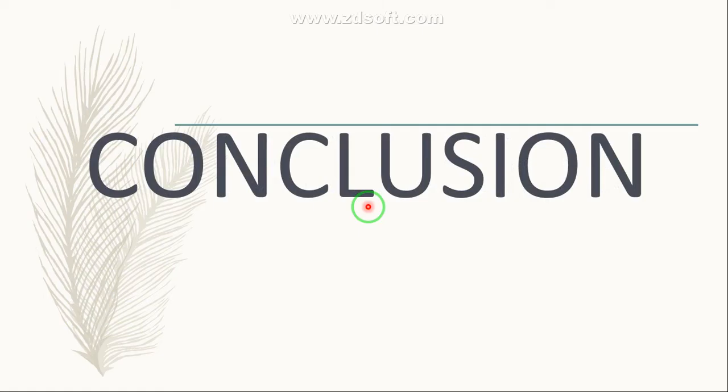So guys, thus we studied delta modulation, how it is generated, how 1 bit per sample is transmitted, and at the receiver by means of the bistable circuit, then unipolar to bipolar converter, integrator, and lastly the low pass filter, we received the signal that we transmitted.